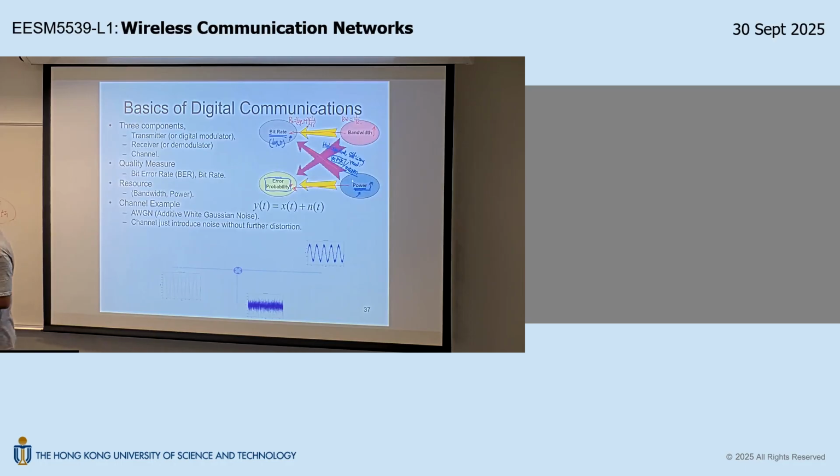Is that okay? So this peak to average ratio, or the power back off, is a penalty. The penalty you need to pay: you back off your transmitter power so that you avoid the nonlinear clipping, so that you don't have this power spectral regrowth. Is that okay? So it's a cost item. How much you need to back off depends on the type of signal, or precisely speaking, the so-called peak to average ratio.